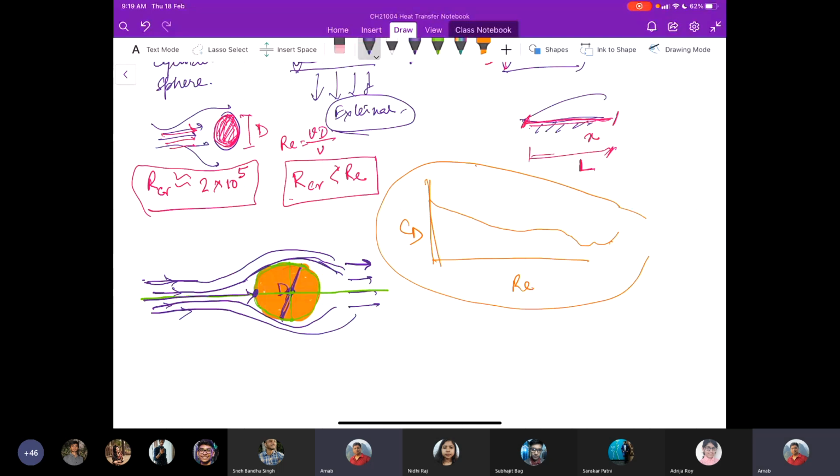So at a very low Reynolds number, low in the sense the Reynolds number is much lesser than 1, the fluid that approaches this spherical object, say the cylindrical object, completely wraps around its surfaces. Okay, and it meets the rear end of the fluid at a certain point.